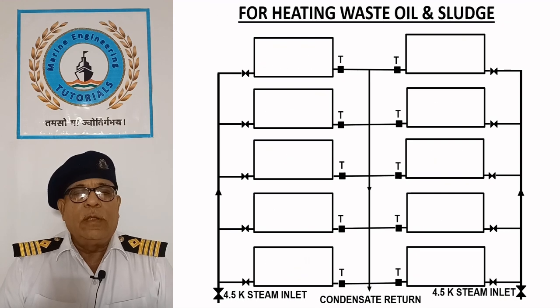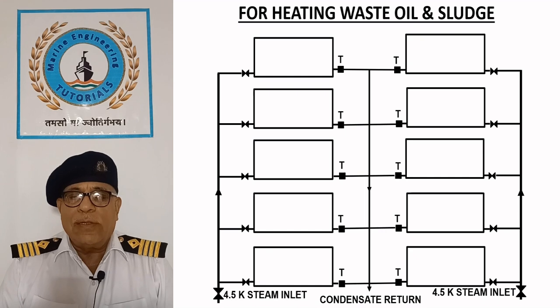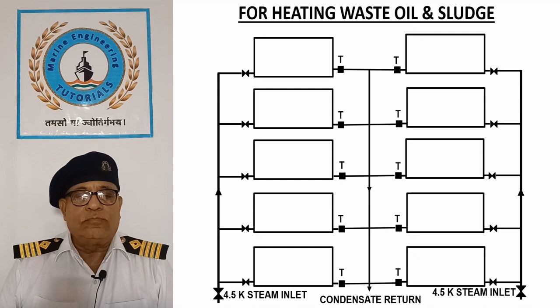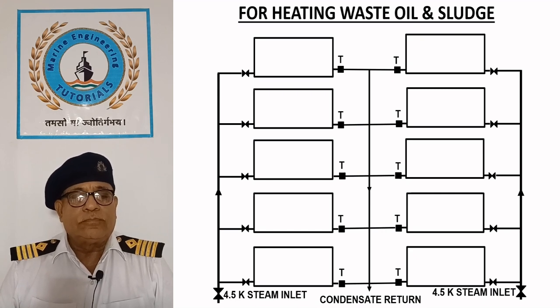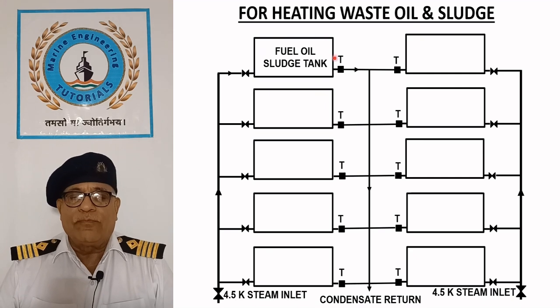For heating waste oil and sludge. Waste oils and sludge generated on ships are highly viscous and require preheating before disposal or transfer. Fuel oil sludge tank.